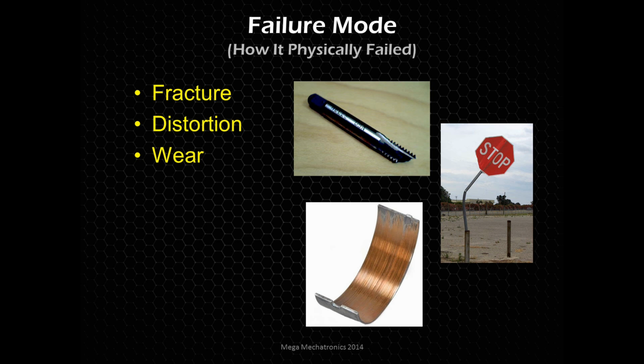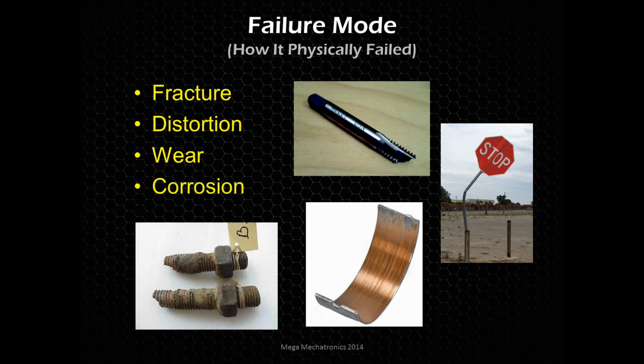So this is a bearing that's probably from an engine. When a rod bearing blows out, you start heating up your crankshaft, and you can even break your crankshaft from the excessive heat, which ruins your heat treat and fatigue protection. Then you overstress it and it breaks. So wear can lead to failures, inefficiencies, and catastrophic failures as well. And corrosion can definitely lead to excessive wear, distortions, and most likely fracture.